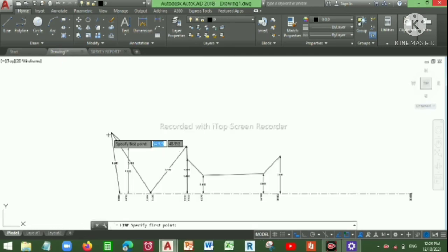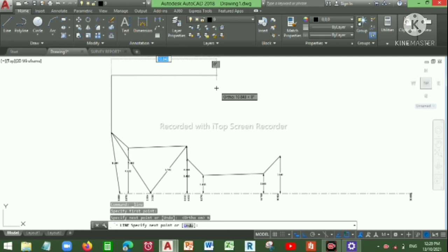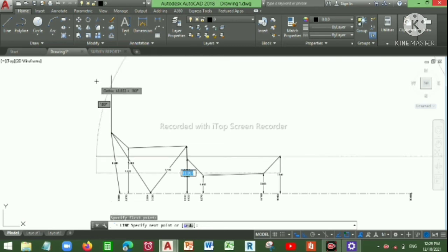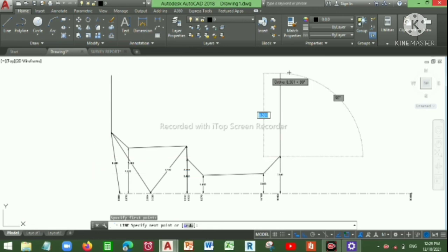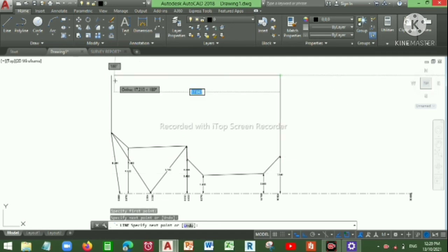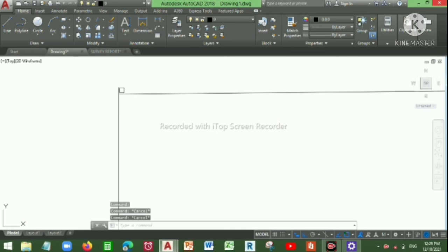If you know the dimension of the side building, you can turn on ortho mode and draw those required dimensions, let's say 6, and go from up here to your required dimensions, click on it, close it, and you can put on all your required dimensions, required hatchings, whatever you need.